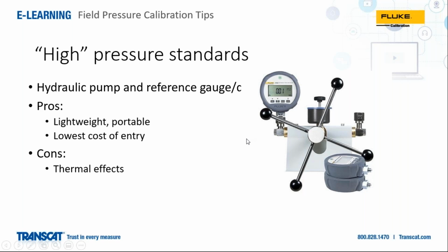The primary way that this is dealt with, by the way, is simply dwell time, waiting for the system to stabilize. This is often seen as a leak or instability, especially with folks that are used to using a deadweight tester. The cure for that is simply time. If the system is apparently drifting, especially as a result of an upward pressure excursion, waiting for temperatures to equalize is the solution.